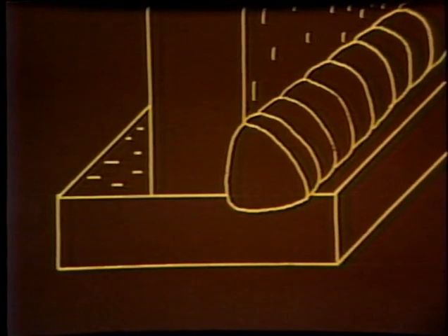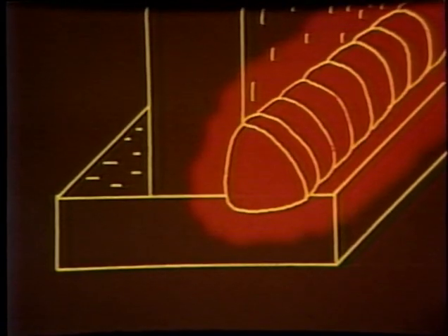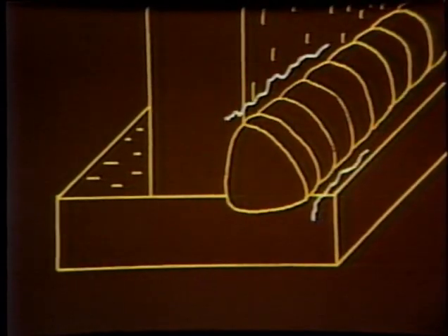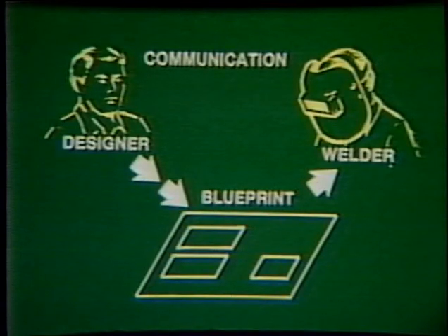When a weld is too large for the joint design, more heat and residual stress is present, which can lead to weldment failure. Excessive welding is also wasteful and time-consuming and may be objectionable in appearance. The most common cause for size-related discontinuities is simply a lack of communication to the welder.